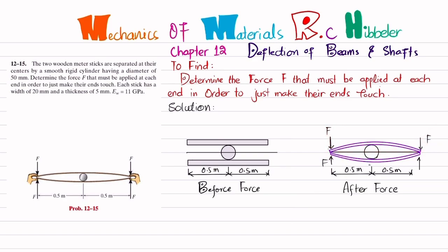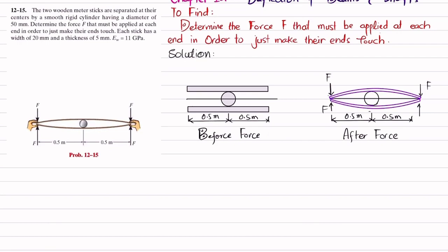So the first step is that if you focus on only this portion, this portion acts like a cantilever beam having a point load at its end. So we can model the problem like a cantilever beam.